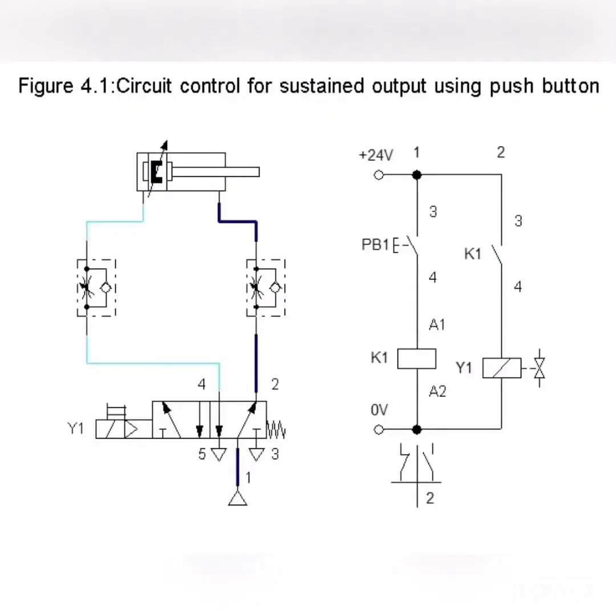For figure 4.1, cylinder A is first in a rest position as the 5-2-way actuator valve is being blocked from reaching the cylinder A. Next, when the simulation is in run mode, there is air pressure inside the cylinder, but somehow the valve does not allow the air to flow through it. Therefore, the airflow runs only from the compressor straight to the valve. The function of the spring is to allow the compressed airflow to fully retract the cylinder.